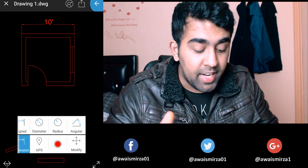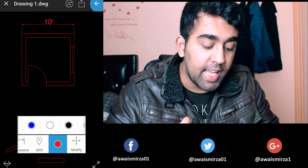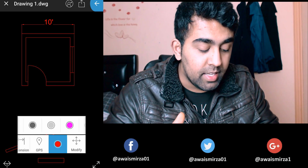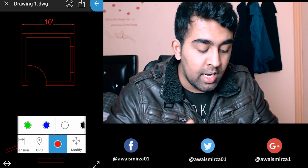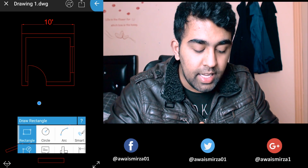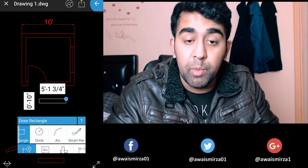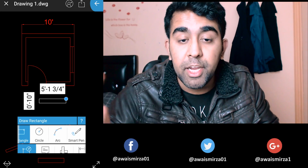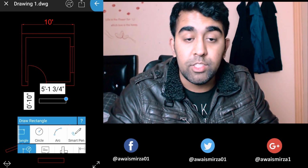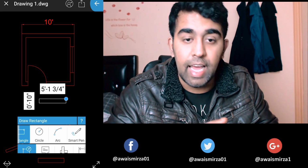Next we got layer panel, right? So if I tap here, I've got green layer, blue layer, white, black, all the layers available. Okay, so if I tap on the white layer, and now if I go to my draw panel, draw a rectangle, it's going to be on that layer. Okay, so the layers are very important in AutoCAD as well. So if you bring your file, you can edit your 2D plan here, a complete project available on your AutoCAD desktop software. You can bring it here and edit it.